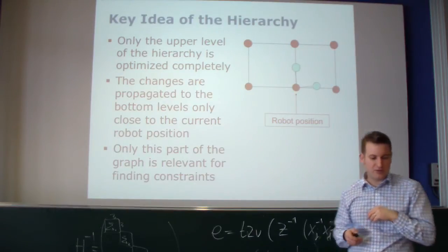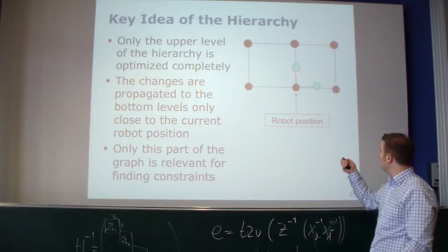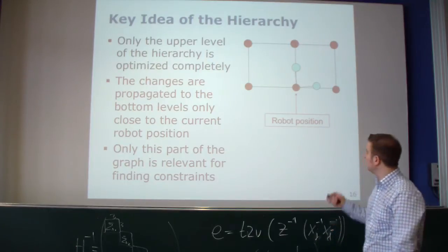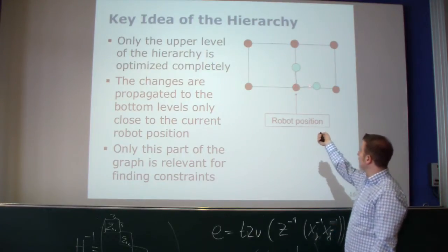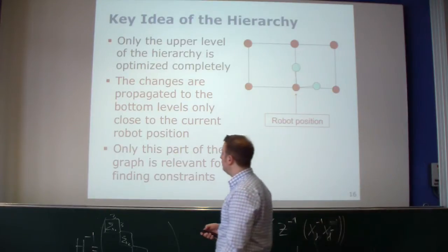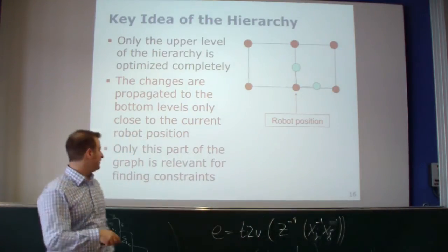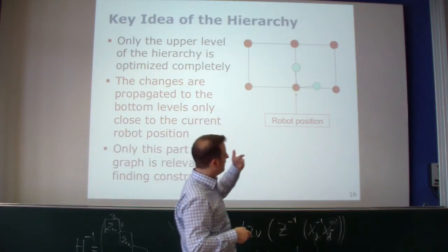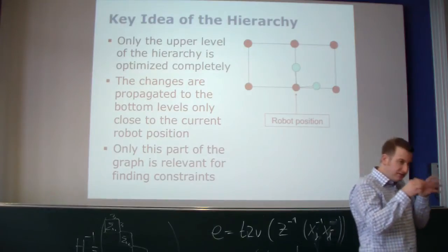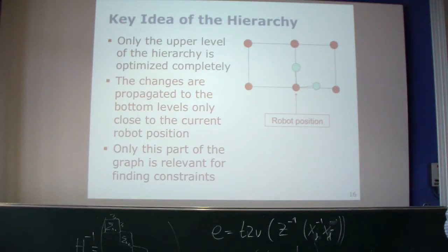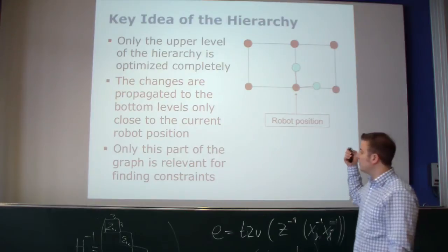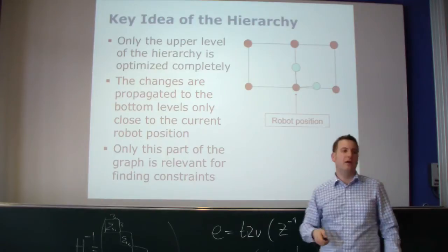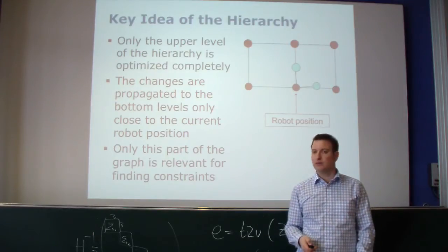So I had these originally two nodes. So this sort of position, these were the kind of neighboring nodes. I had my pose graph on the lowest level. So it kind of does the transformation of these nodes down here. And maybe I can use these nodes now on the lowest level to render my local map accurately, optimize it on the lowest level to make them more accurate, just on a very local scale. And then I can actually build a local map from this one over here and then check what is the uncertainty of the other nodes to check for the closures.